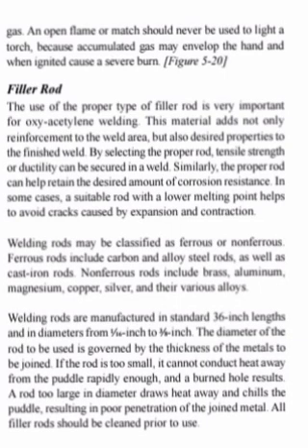An open flame or match should never be used to light a torch because accumulated gas may envelope the hand and, when ignited, cause a severe burn.